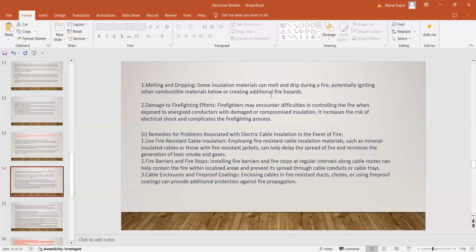What is the job of the electrical officer in case of fire? Switch off the power supply. Switch off the power supply for the affected area, so that when the firefighters are going inside with the charged water hose, and if the electrical cables are still energized, it might be possible they are going to get an electrical shock, right?